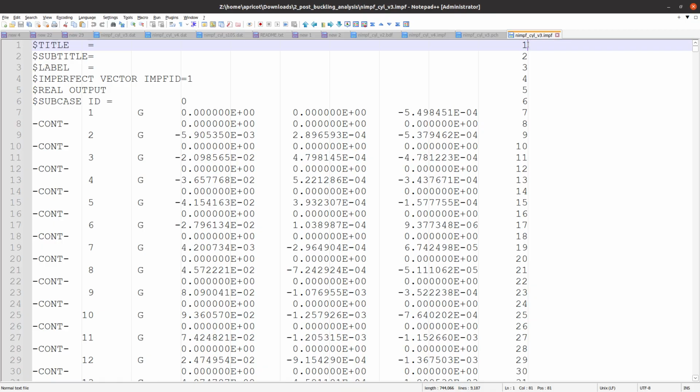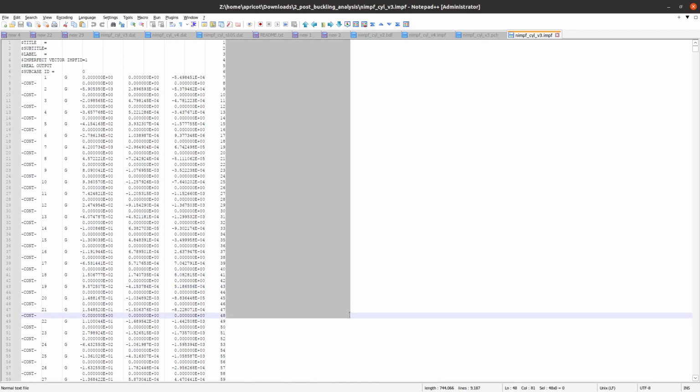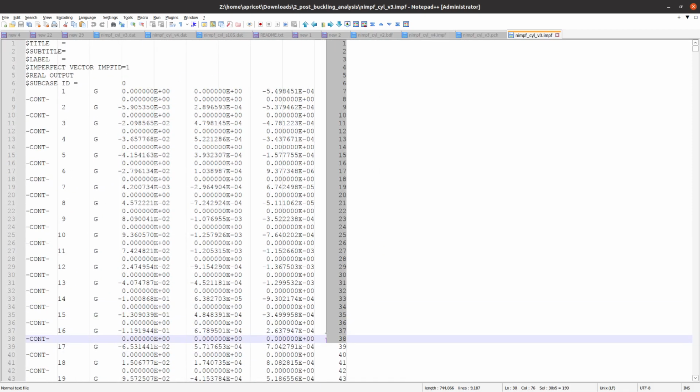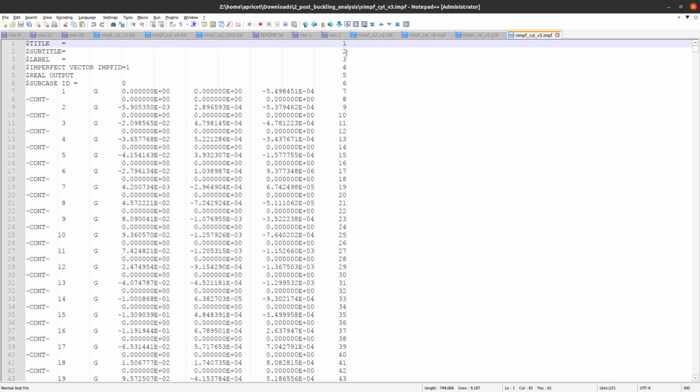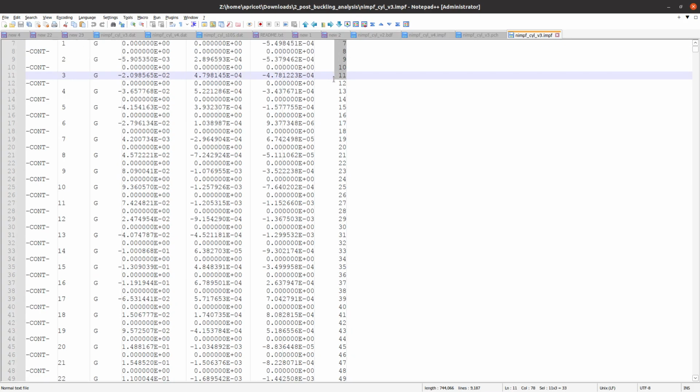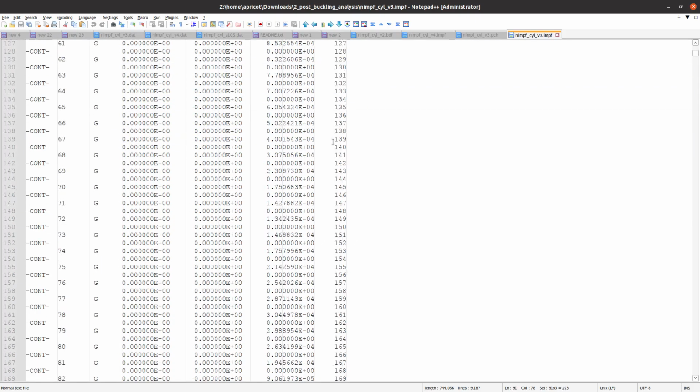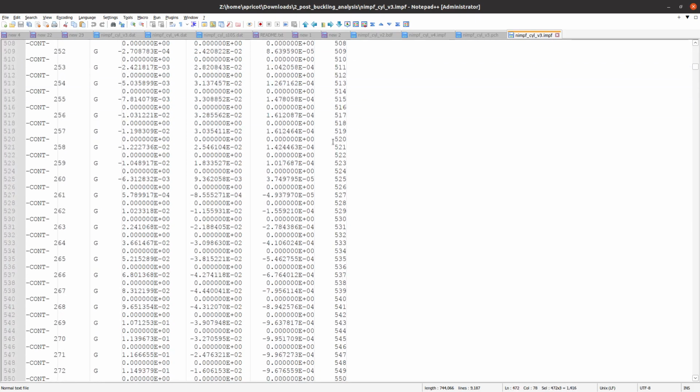And then with the left mouse button, you can drag and select. So here, let me repeat that. Press and hold the Control Alt keys. Move the mouse a little. Let go of the Control Alt key. And now you're in this mode where you can select vertically data.